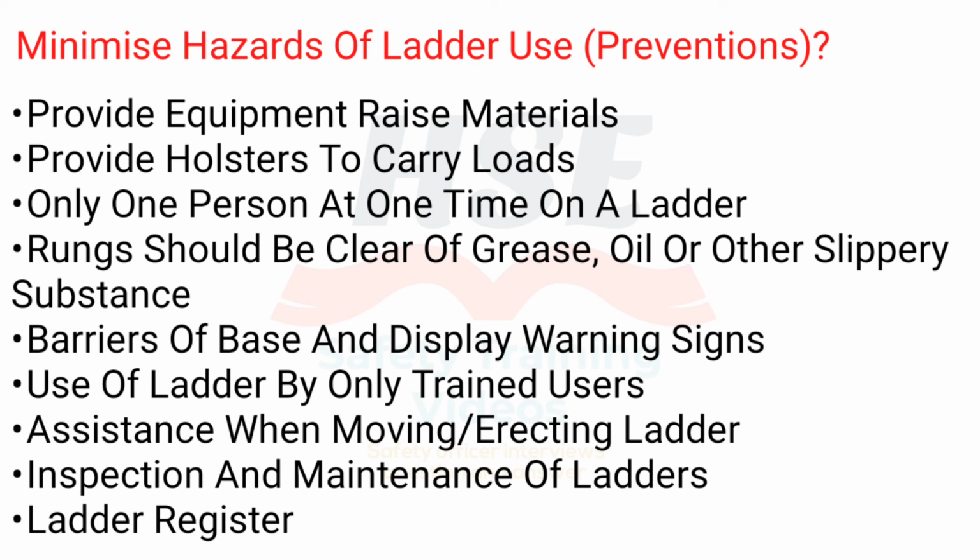Place barriers at the base and display warning signs. Use of ladders by trained users only. Assistance when moving and erecting a ladder. Inspection and maintenance of ladders. Ladder register.